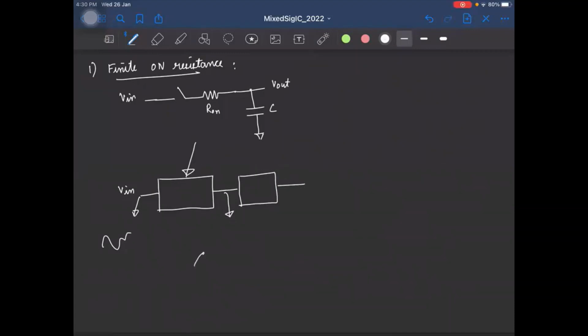So it tracks the input and holds it during half the period, tracks it, holds it, and so on. And when do we process the output of this first track and hold? When its output is held, right? Because only after this time instant the output is sampled, and during this phase when the output is held is when we can process this data, right? So the track and hold used in the second stage here will see an input that is kind of constant.